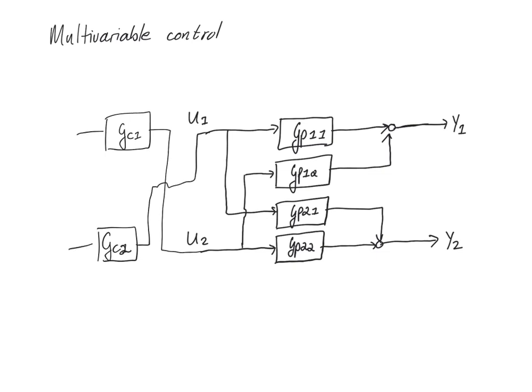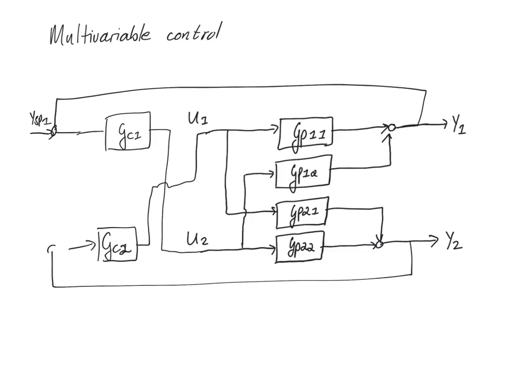All of the other calculations remain the same. So we'll still have a set point, except that this set point will be the set point for still y1, but we are manipulating u2 to do that, and we'll have the same calculations over here. Now we have what is called an off-diagonal pairing, or a 1-2, 2-1 pairing.